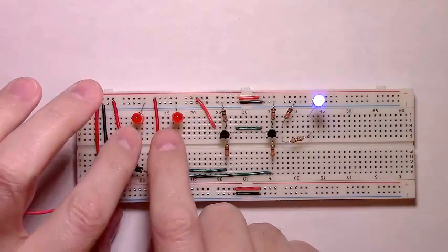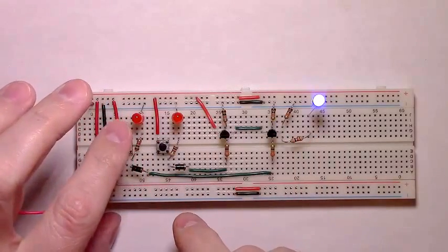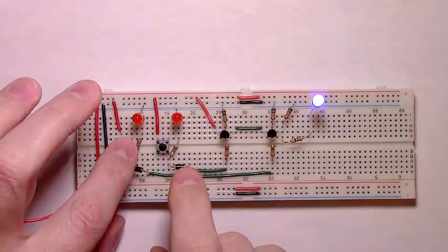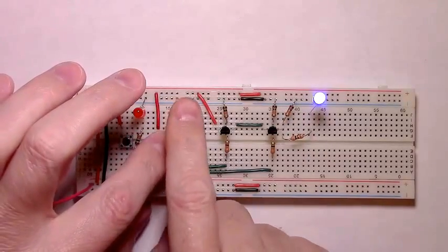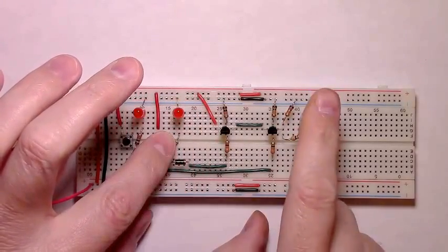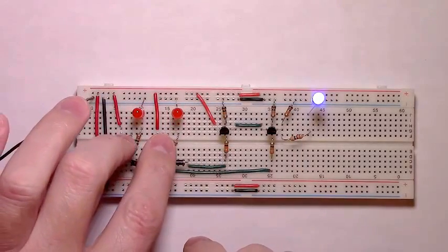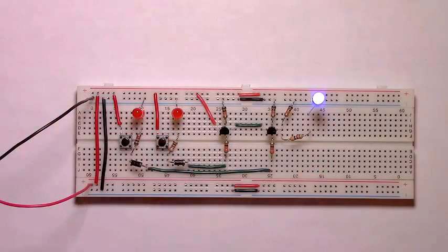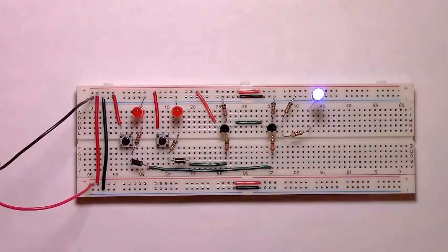When both inputs are low, the output of a NOR gate is high. Now, does it still go through the truth table? If your first input is high and your second is low, the output LED should be off. And it is. The next option is your second input is high and your first input is low; your output should be low. And it is. And then what happens when both inputs are high? The output should be low. And it is. So we've effectively built a NOR gate using PNP transistors and some other components, some Schottky diodes and momentary buttons.